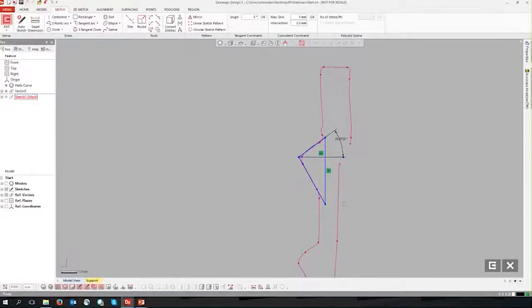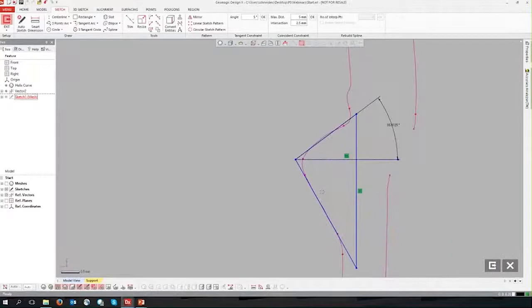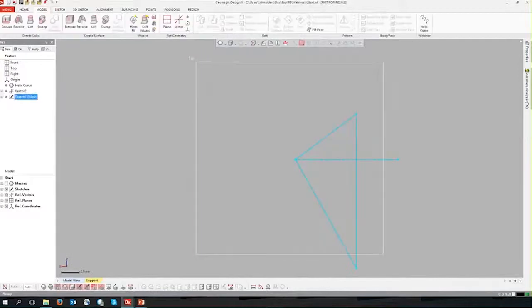So the main point to do at this step, though, to construct the helix is one, make the shape that will end up sweeping, so this will be the thread shape, as well as make the point where we're going to start our helix. So on this part, we have our starting point slightly off the end of our thread where we cross-sectioned it, and this could have been maybe there was a fillet in the original drawing, or this part was worn down, right? So instead of having to make that 3D reference point, we're just going to extract and take this center point as our starting point.